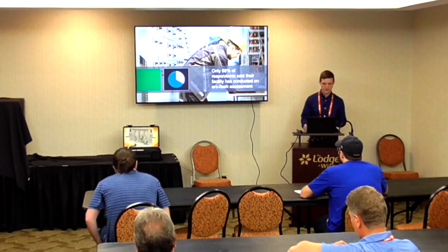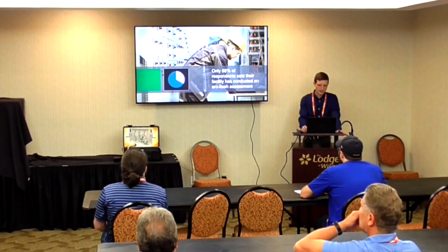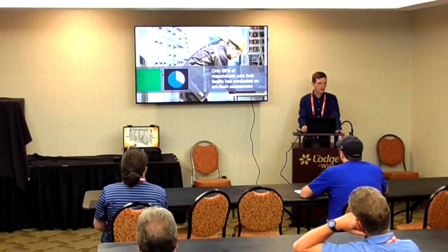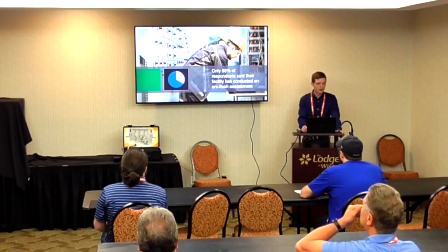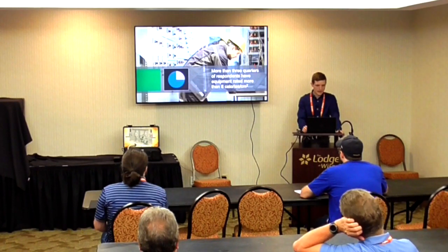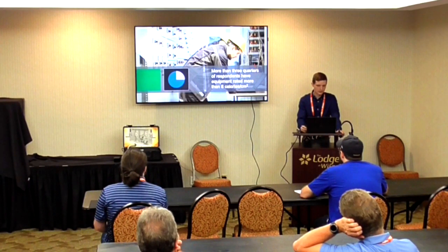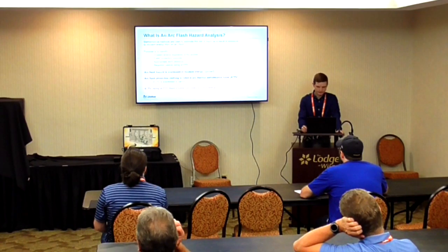The hazard assessments themselves. Just before we actually get into some of that, 66% of the workforce has responded and said that their institute or the place that they work has not completed an arc flash assessment. So you're essentially working with some unknown variables. You don't know how dangerous your equipment actually is. And about 3/4 of respondents say they have equipment that's rated to 8 calories or more. So you're introducing quite a bit of room for error there if the PPE is faulty or if it's not equipped properly or anything like that. Just to keep that in mind.